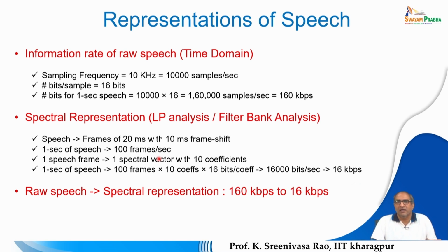Suppose for example, if you apply FFT with some appropriate window, then for every frame, based on the window size of n, we have n values, and then we divide those n values into bins, the number of bins as per our requirement. So that way each frame of speech can be represented by a certain number of coefficients, and those coefficients refer to the spectral energies if you perform a spectral analysis.